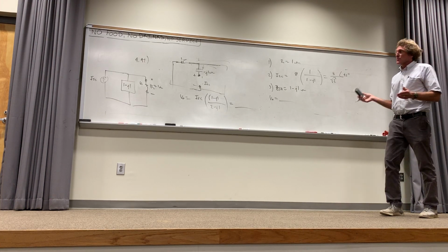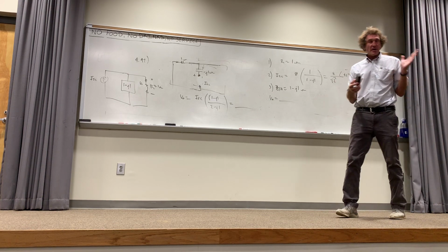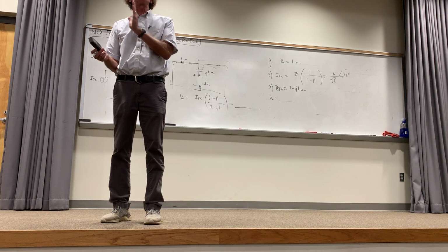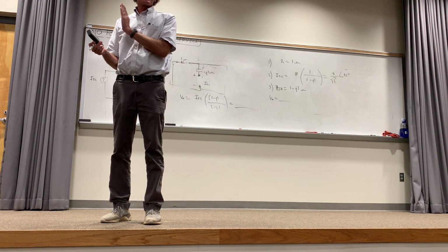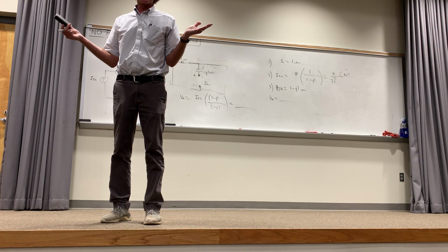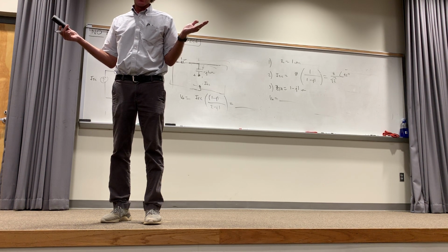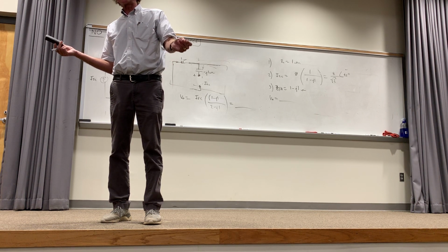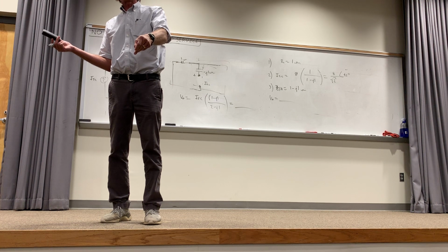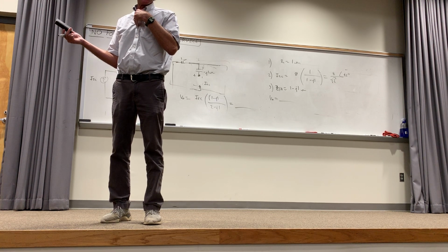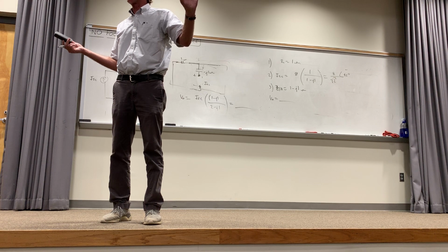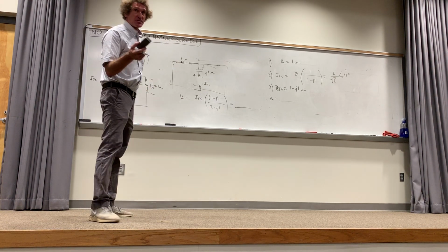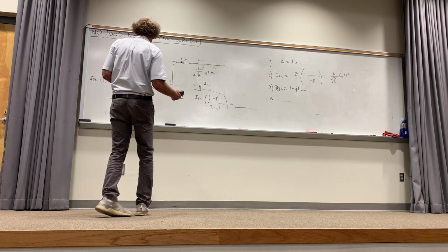Now Norton, if you really want to know the truth, when you have a current in parallel with impedance, that can be transformed to a voltage in series with a resistance. So if you got one, you got the other automatically. Do you follow me, class? Everybody follow me on this? This is important. And you will be asked about this kind of stuff. All right, but I tend, for the record, to lean towards Thevenin. In general, in my opinion, it's usually easier, all right? Because when you have an open circuit, it's easier to get that voltage than a short circuit current, right? So just for the record, if you want to know how to win it.